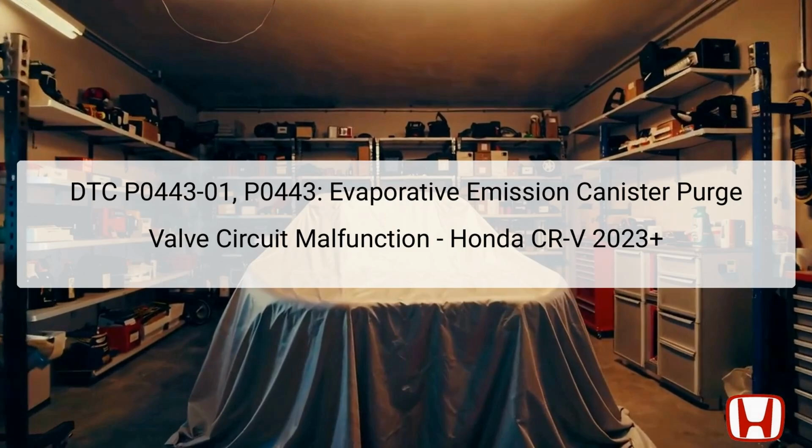The Diagnostic Trouble Code, DTC P0443-01 and P0443 indicates a malfunction in the evaporative emission system, specifically concerning the canister purge valve circuit. This system plays a crucial role in controlling and minimizing harmful emissions by managing fuel vapor from the fuel tank.